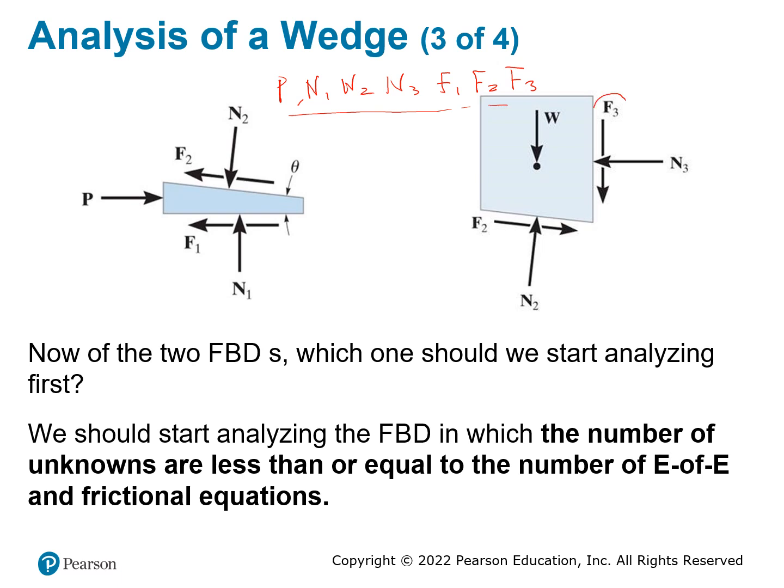Now each one of the friction is going to be related to the coefficient. It's going to be equal to mu s times whatever the normal force is against that. So then you have 3 frictions, so you're going to get 3 equations. And then we need to use the summation Fx, summation Fy for each one of the cases.